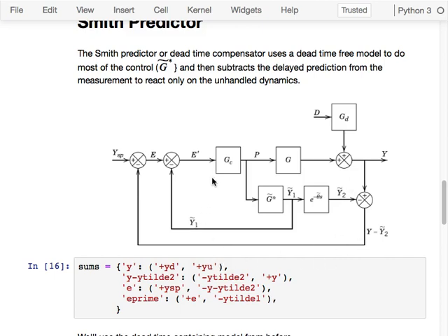So it's quite cool, because it means you could, in principle, easily substitute a nonlinear model. It's the first time that we've seen that kind of thing happen. That hasn't been the case for any of the other strategies that we've used, except for feed-forward without time delays. You'll remember that we could use feed-forward without time delays. We could use nonlinear relationships quite easily there, because we could solve those equations.